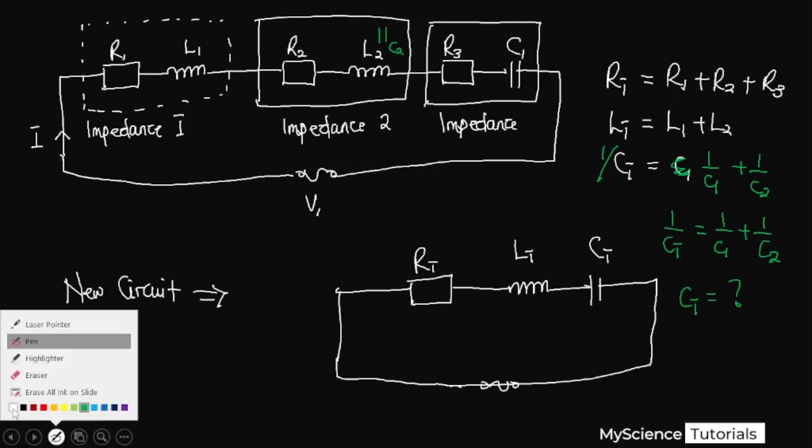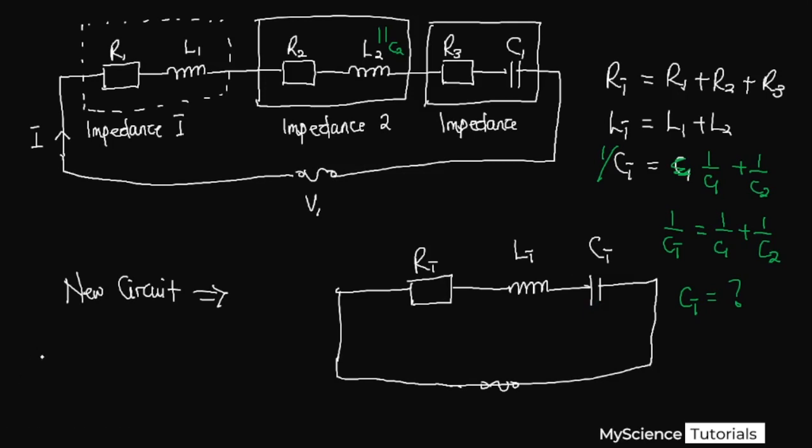So with this basic introduction, and knowing the formula for calculating impedance when we have a resistor, inductor, capacitor circuit, as we saw in the previous video, our impedance is equal to the root of R squared plus XL minus XC, this guy squared. So this is how we find the impedance in case we have a resistor, inductor, and a capacitor in series.